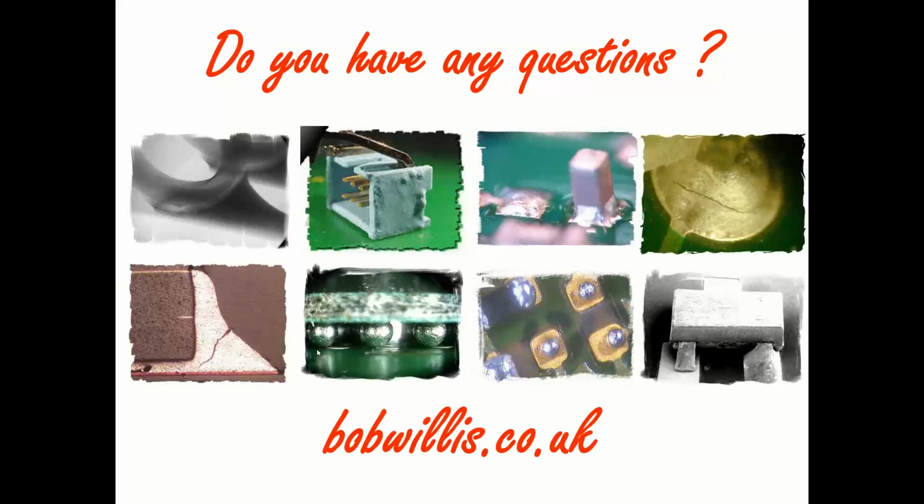So if you go from -20, -50 to +100, 120, as you change your temperature, your material, whatever it might be, expands and contracts at a rate. The same as solder joints, PCB laminates, etc. So if the material you're using expands at a greater rate than the solder joint and the component terminations, which may be copper, then you're putting strain on those joints all the time.